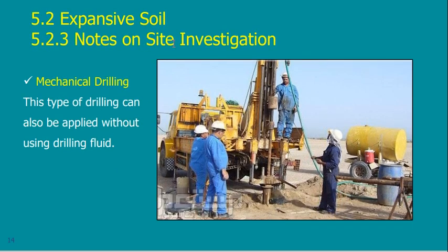This is the boreholes. This is the normal machine for mechanical drilling. We can drill holes using this machine. And if you see next to this machine, there is some kind of arrangement that is used for the cooling water. Here the water is in a pit, and it is circulated to cool the machine while drilling. Of course, if we use this type in a site investigation, we have to use it without water to be able to get good samples.